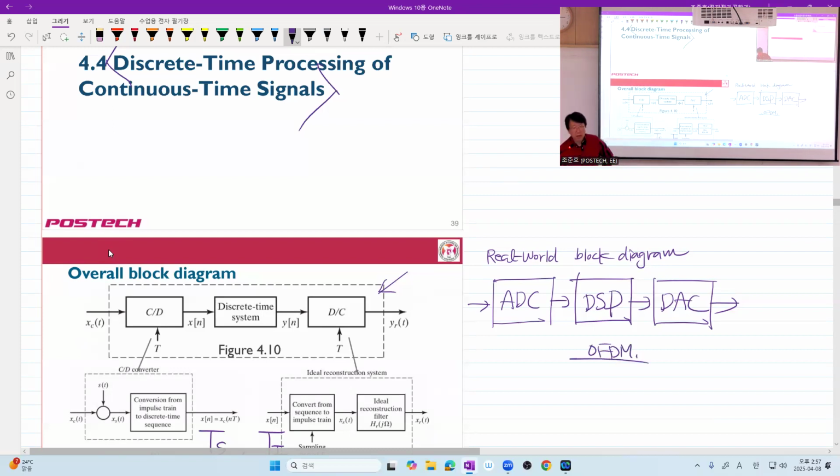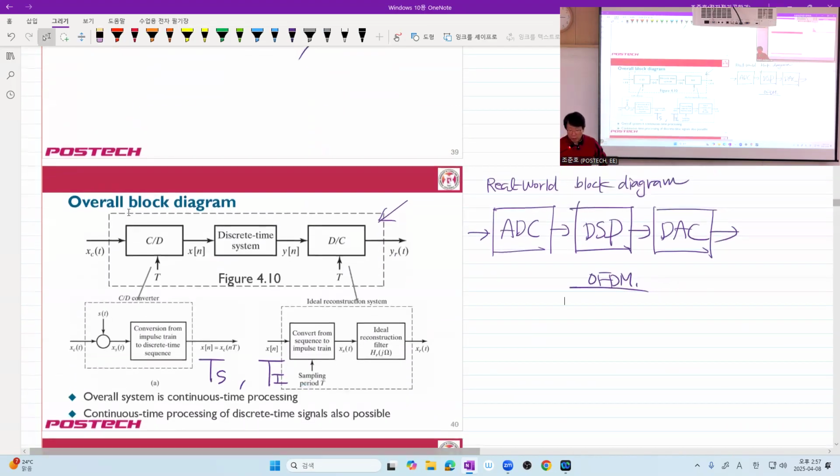Many of you may have taken a communications course. In OFDM, with, for example, 600 subcarriers, is it possible to do OFDM using analog components? You may need 600 local oscillators whose phases are perfectly synchronized, and that simply seems impossible.